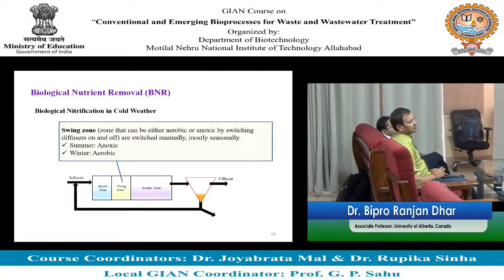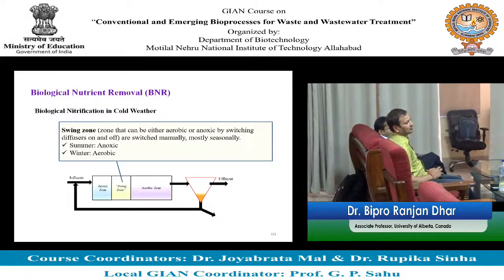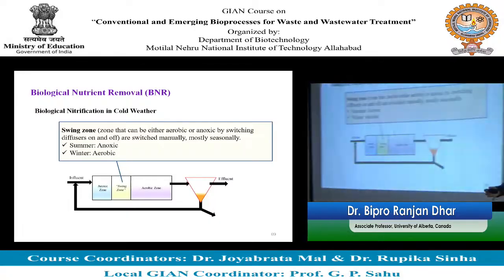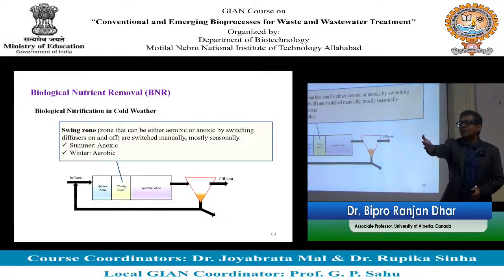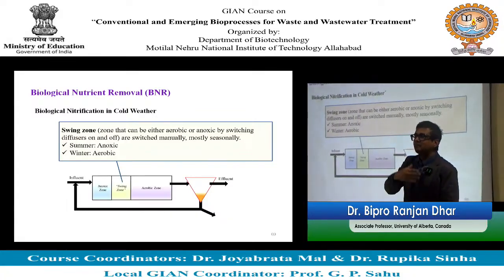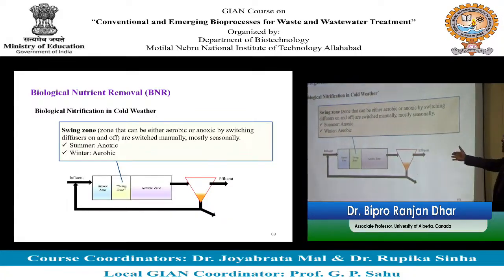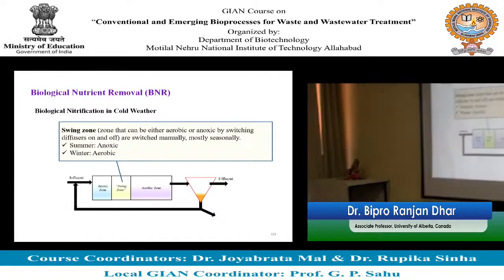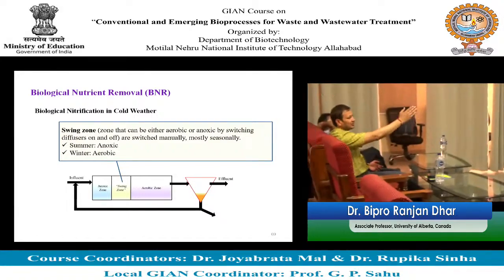So that's why it's better to have the anoxic zone first, and then the recycled nitrate will come to this zone through diffusion. Otherwise, if I put aerobic first and anoxic in the second stage, there is not enough BOD. That means I have to provide BOD, like, as you mentioned, you have to add glucose or ethanol, right? So that's why we put the anoxic zone first. The nitrate comes through diffusion, meaning there is no barrier in between.